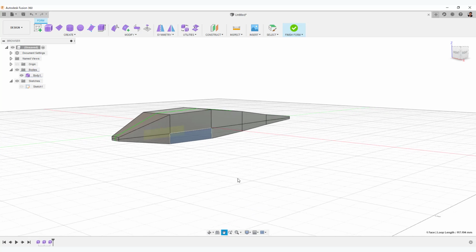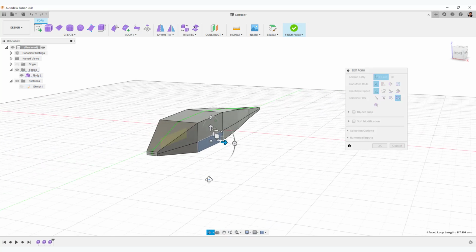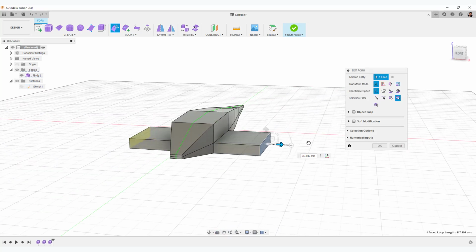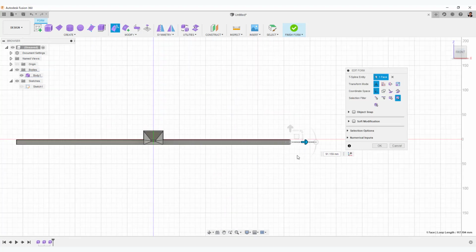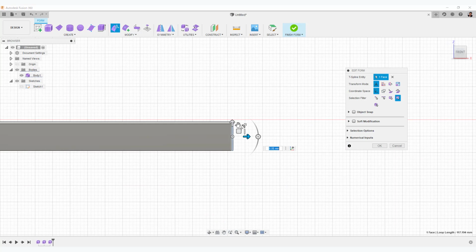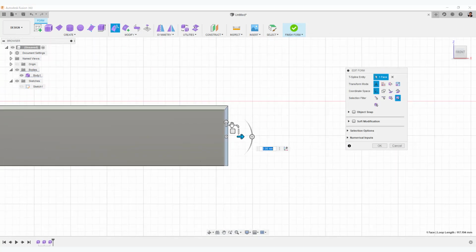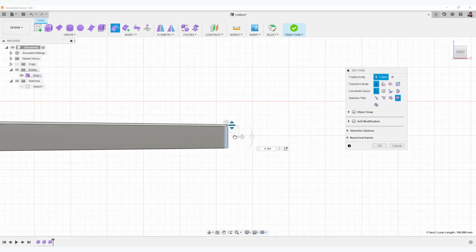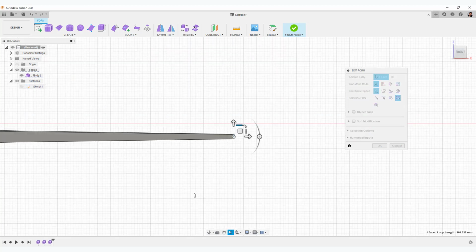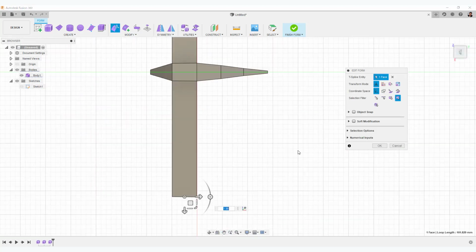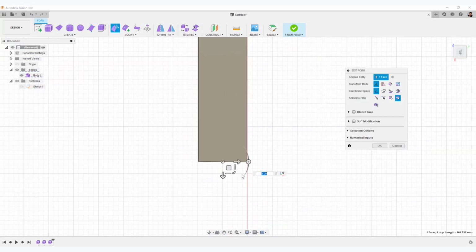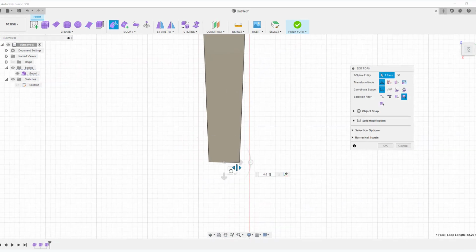Select this face in the block display. Then press Alt to extrude. Roughly the length is fine. Select this icon. This can only be scaled up and down. Then change to top view and select this icon. This can only be scaled left and right.